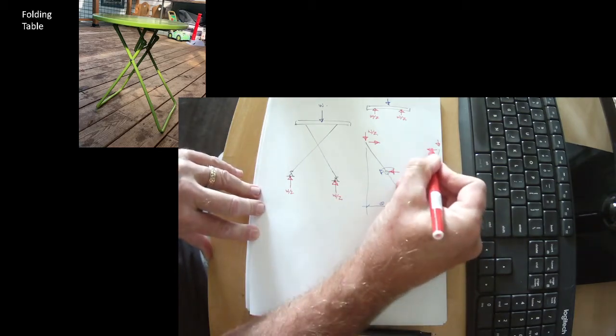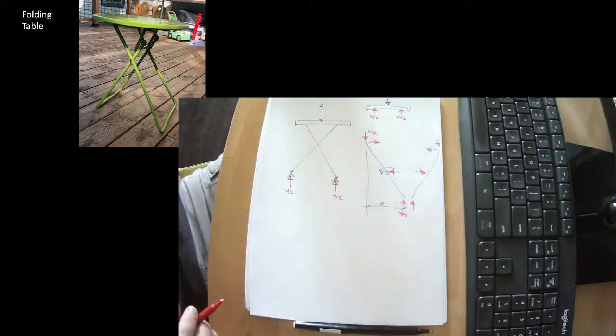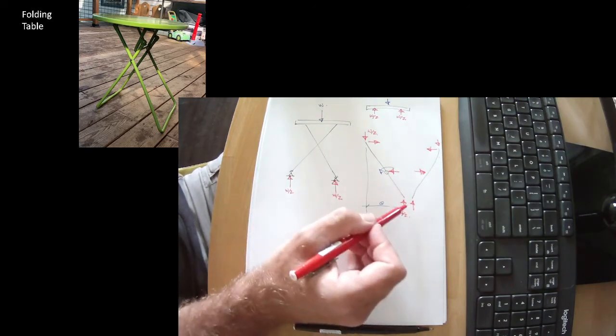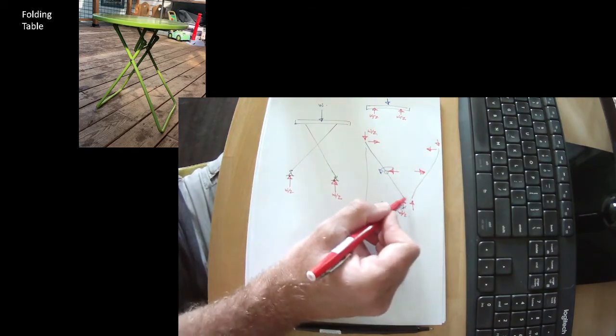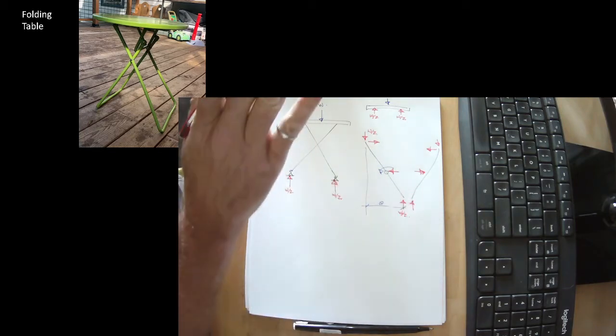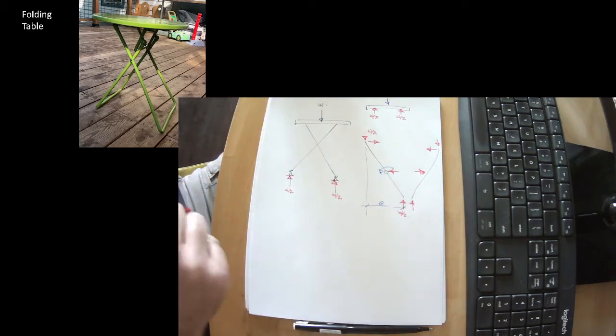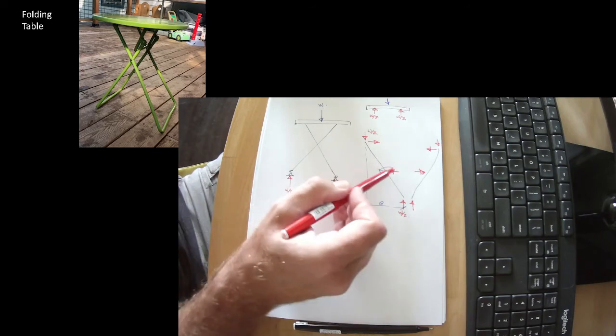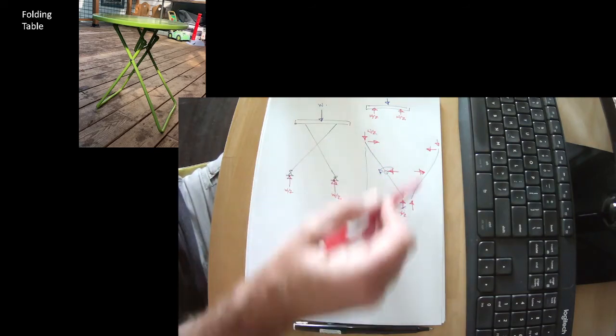And we know that it has to be the mirror image of that free body diagram. We know that we can't take a horizontal force out at the base. If we could, that would be fine, but we can't. We'll treat the base as frictionless. Even though it has friction for wind, we treat it as frictionless for gravity. So this is our diagram here.